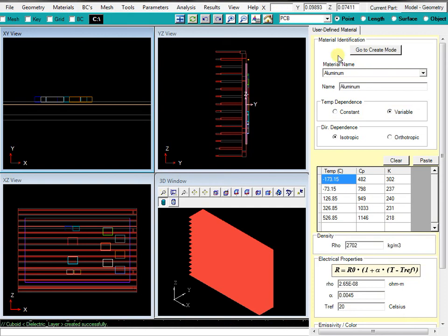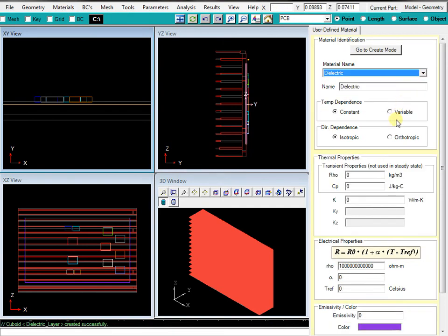And before doing anything else, I'm now going to set that material property here. I'm not worried about transients, so I don't need to set these. This is set as a full insulator. Realistically, the properties are going to be a lot less than that, but in ElectroFlo, something either is a conductor or it isn't. You won't see a breakdown at a certain point of voltage. So if it's a conductor, it is important just for determining the Joule heating through that substance, so the I²R heating. If it's an insulator, it doesn't actually matter what properties you're using for electrical properties as long as they're greater than 1.